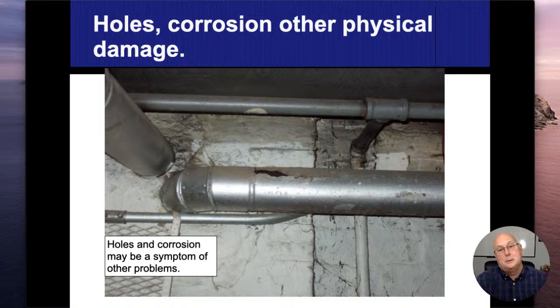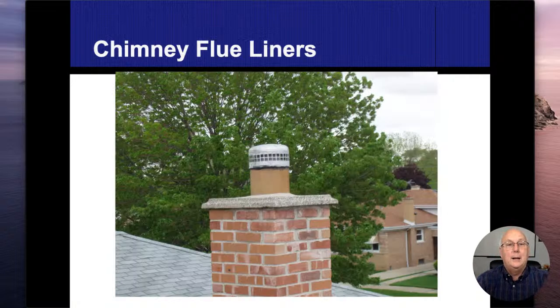You keep these pipes, the bigger pipes, and you start using them on the more high efficiency units. There's a lot of condensation, a lot of moisture. And if I'm not drafting that out, moving it quick and getting it out of the house, it just starts to rust and corrode these pipes. This to me was, again, another obvious defect. We see a big corroded hole in the vent connector that's just spewing carbon monoxide into the house. Nobody was going to argue with this one when we called it out.